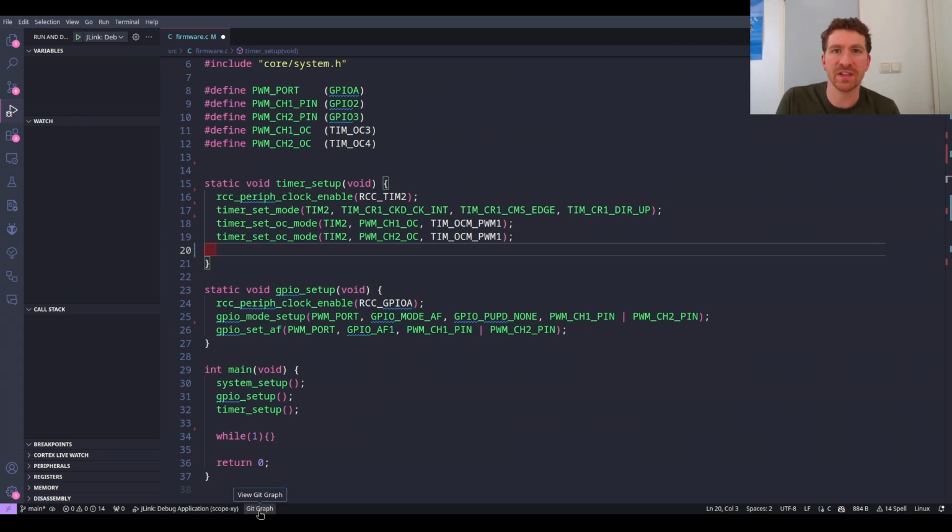So that gives you fine-grained control, and we want 256 fine-grained increments in our PWM. That's how we're going to set it up. And there's actually an equation that tells us what the frequency of the PWM is. The frequency is the clock frequency of the chip divided by the prescaler, so that's the value of the clock division, multiplied by the period. In both these cases these are actually minus 1, because you would never specify a 0 value, so you don't waste the space. But basically, this is how we work out our frequency.